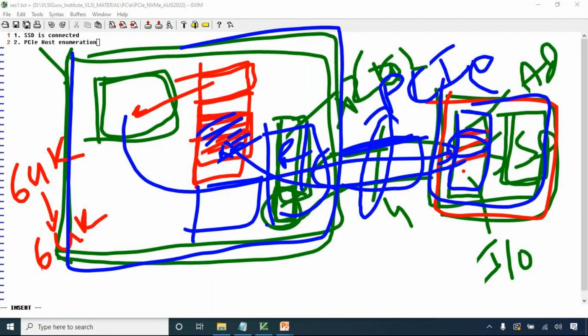I think where you're coming from is the USB mode. How does your USB interact with your non-volatile memory? And here you're trying to understand how NVMe comes into the picture when you have PCIe interaction. USB has the whole mass storage controller protocol and the SCSI controller. On the PCIe side, we do not have it. NVMe has been developed as a technology to interact with your memory over PCIe. Earlier, for memory you already had SATA. For PCIe, you do not have that. That's why you have NVMe technology.